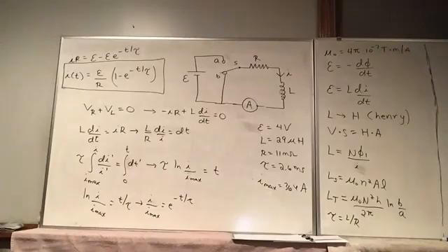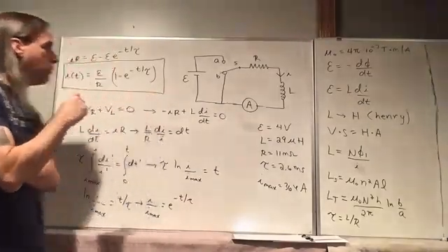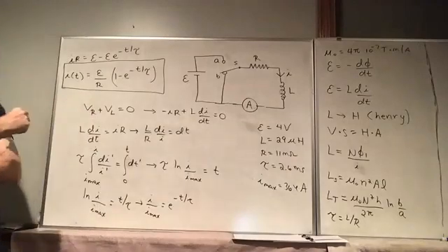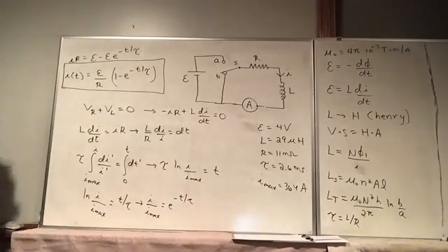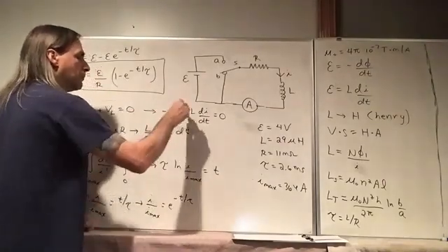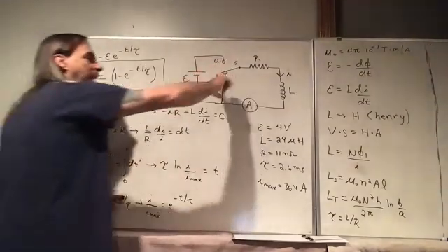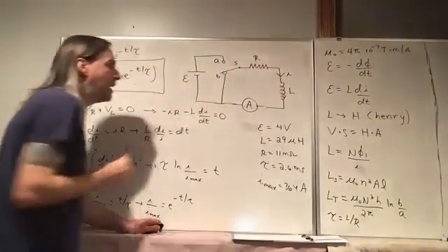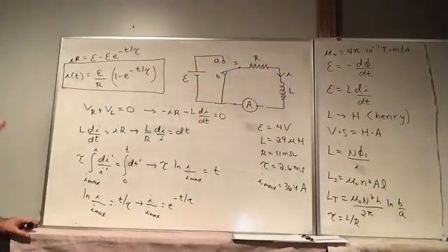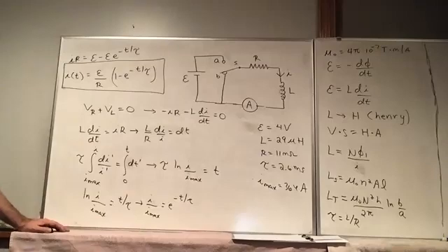Oh, okay. I made a mistake in the beginning, and I did it in the worst way possible, right at the start. This should actually be negative. I thought it through and said the induced emf is fighting and trying to drive the current in the same direction. So overall that whole term should be positive, but di/dt itself is negative because the current is decreasing.